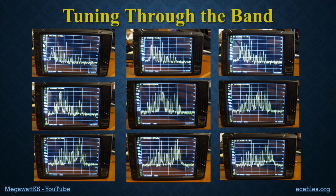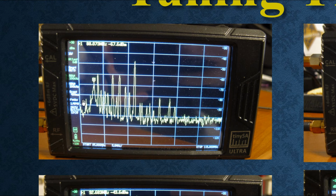But now let's look at what the mixer would be seeing as we tune through the band. So here's what we just saw. This is what's going into the mixer. And there aren't that many strong signals that could cause intermods, and this guy has been elevated so much that even if there are intermods, it's not going to hurt us.